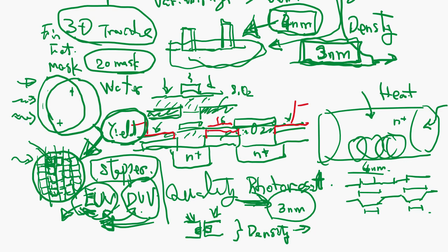Say if you have 100 million transistors, the transistor size is determined by what? The channel size or metal size? It could be photoresist limitation. So that's density. Even when the transistor is small, density is lower in this case. The transistor is small, so the transistor characteristics will be faster and less power required. But the density cannot be big. So overall technology is necessary.